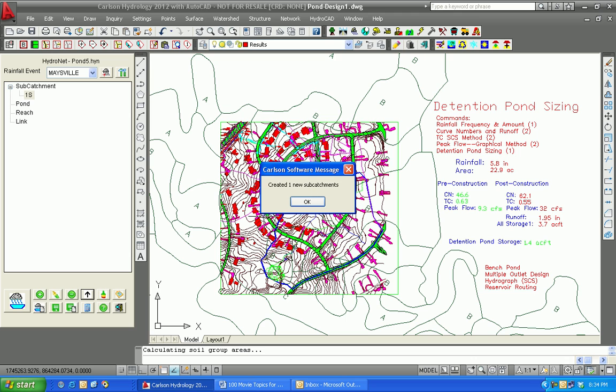You will get a little problem here if you use any of these layers elsewhere as text on the drawing. Then it'll try to use that text and apply it to soil types and other things. So be sure that the layers associated with this hydrology design are used only for their design purpose. Now, if I right-click the 1S that's come up, it found that watershed by name.